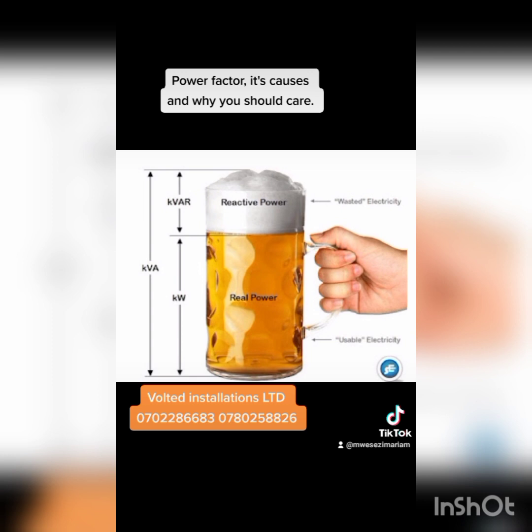And the next reason to improve your power factor is that when you increase the power factor, you increase your system capacity. So you increase the amount of KW, the real power you use in the system. And you also increase the efficiency and the voltage levels of the systems.